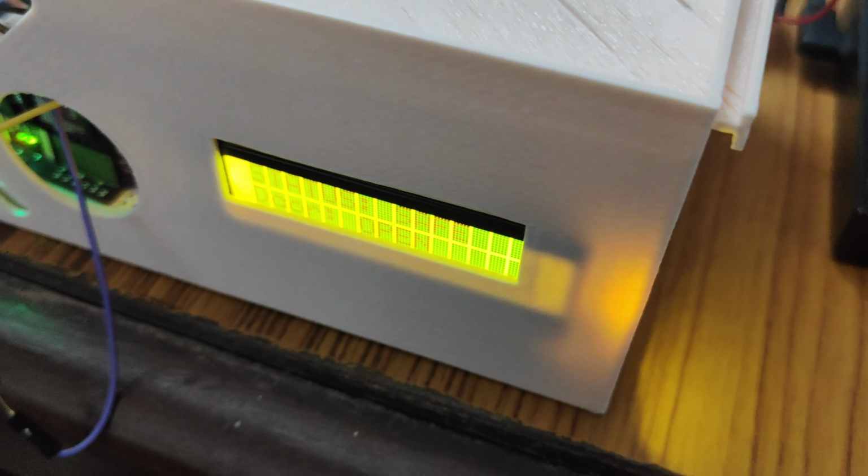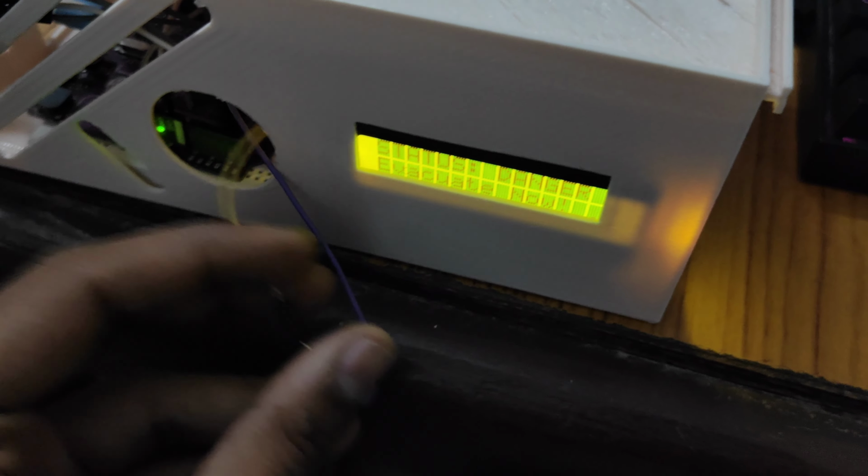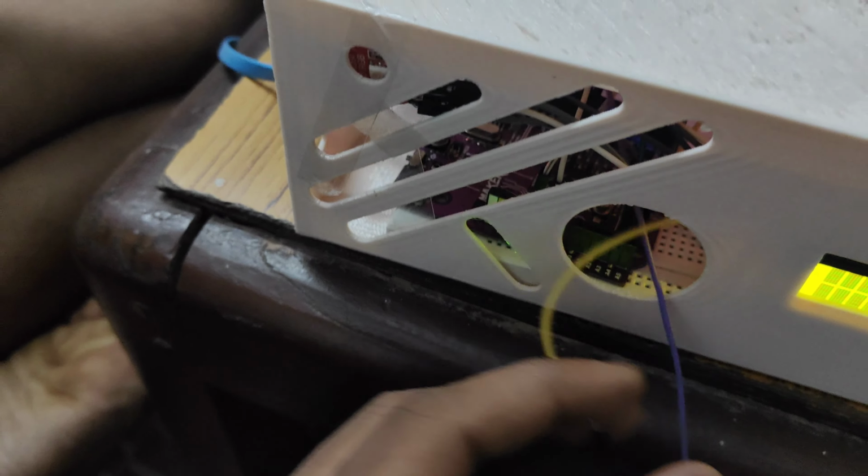So now we can check the vibration sensor. If we were to start vibrating, we are going to get a red signal which indicates that the system is unsafe, and we are going to also see that here. We can also see that in the LCD display, and the buzzer is also going on as we can listen. Now if we were to stop vibrating, the system goes back to being safe and there is no vibration, and the system goes to green state.